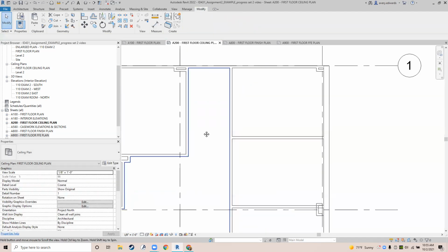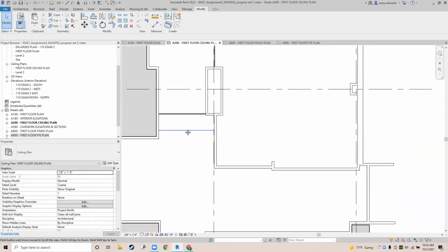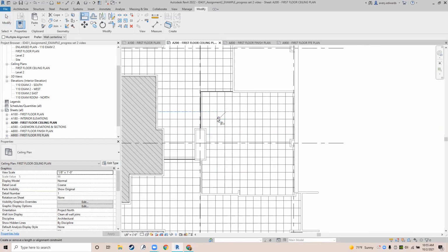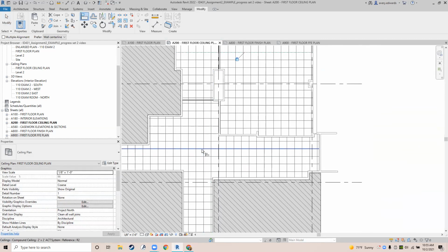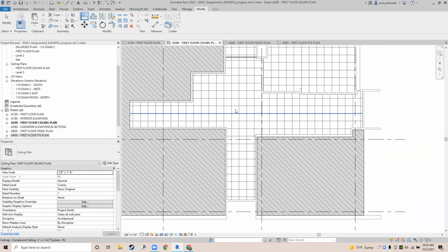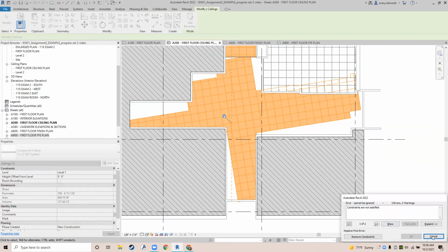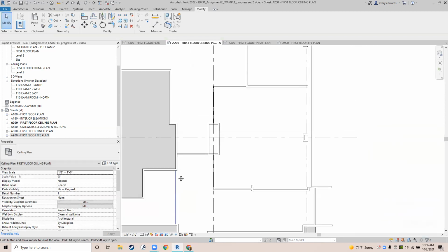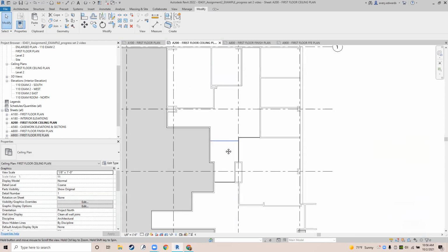Okay. So we're going to keep aligning through our doorways. And remember, when you're aligning by the grid, it's just moving the pattern inside of your ceiling. Because if I take the ceiling and rotate it, obviously it's moving the entire thing. No, we don't want to do that. We just want to move the pattern inside the ceiling boundary. Okay, so I've got my ACT ceilings aligned.